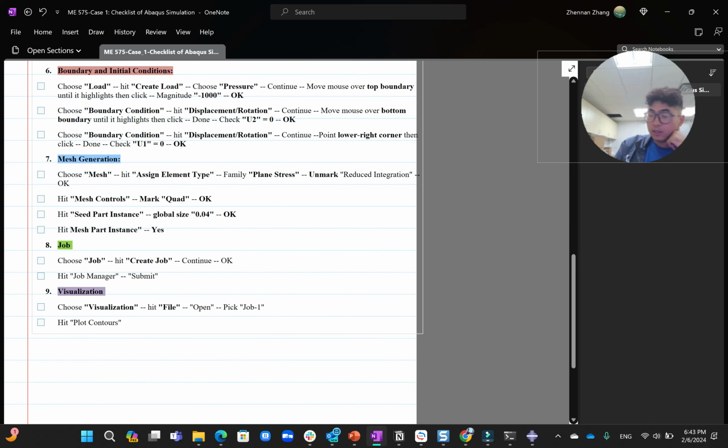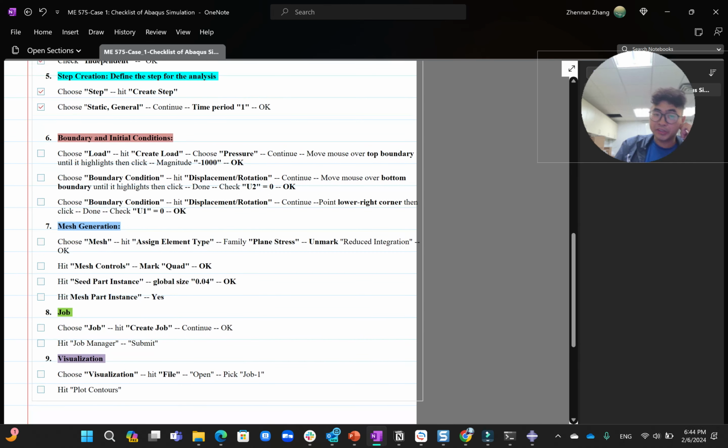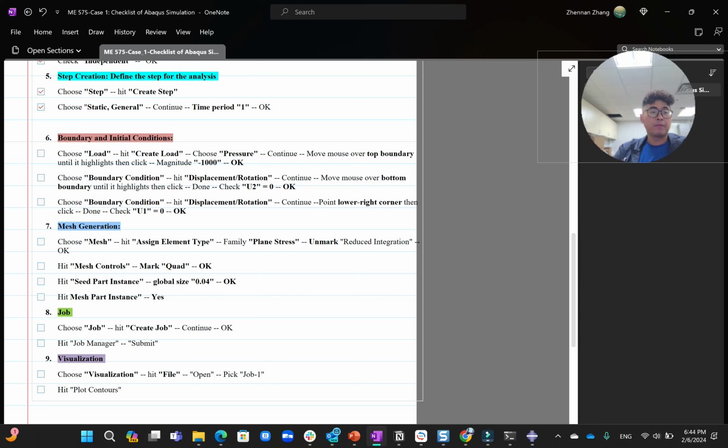Okay. Another step is quite important. You need to define the boundary conditions. In the simulation, boundary condition sometimes is a difficult part, especially for some very complicated geometry. If you cannot define the boundary condition well, you cannot even run the simulation.